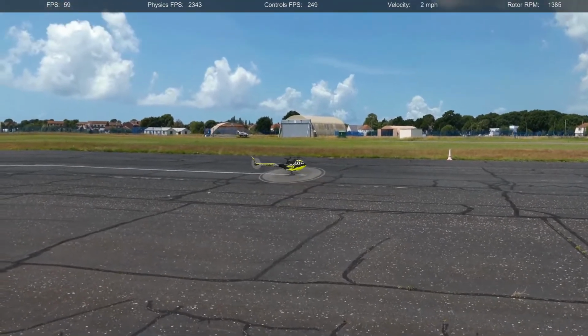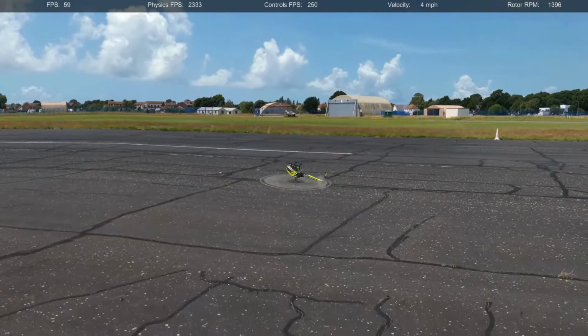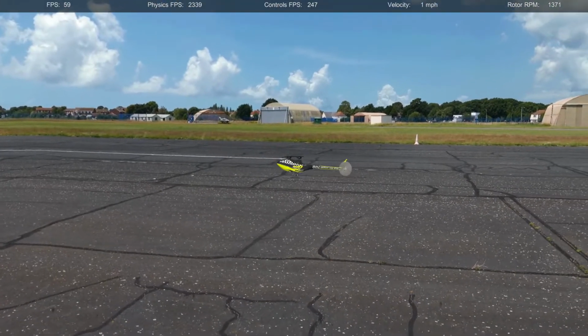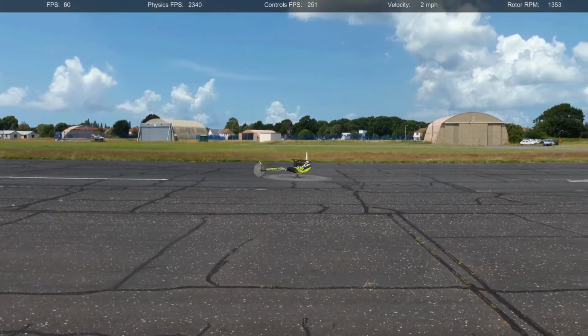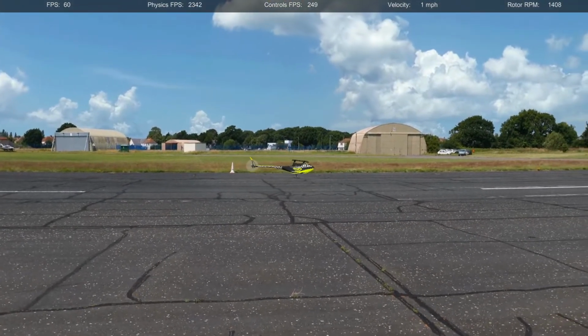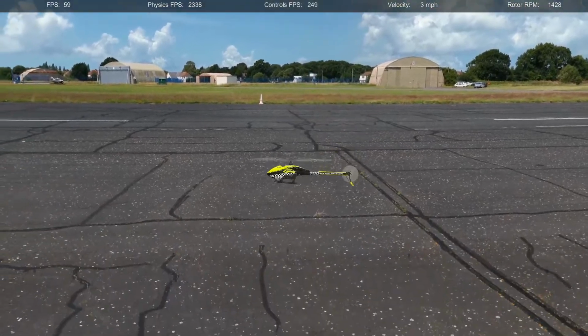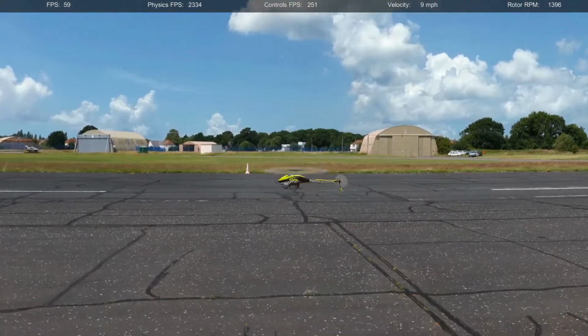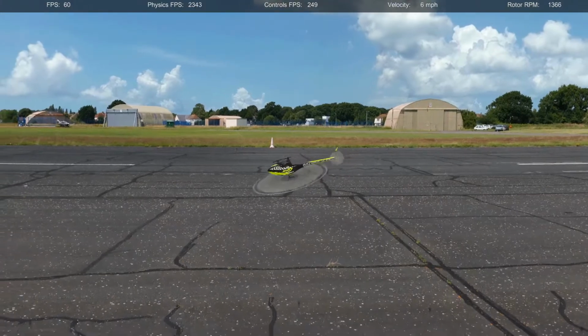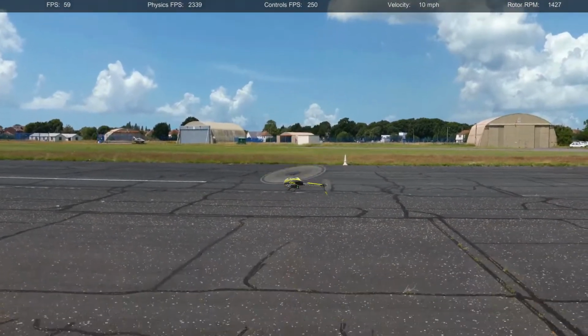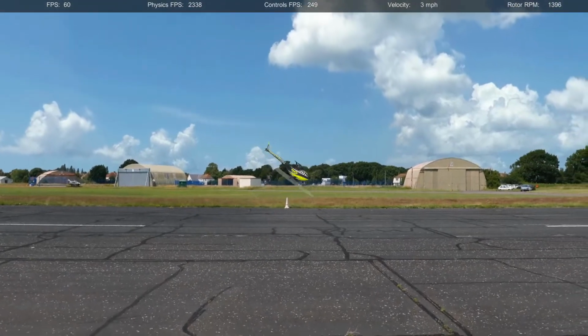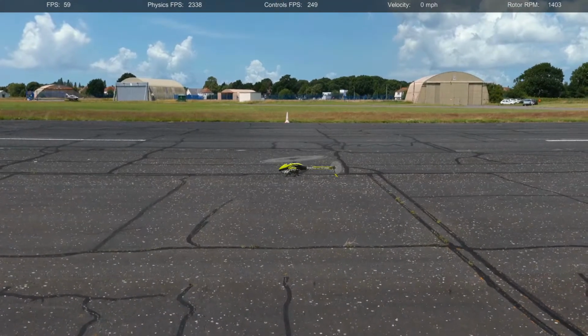And we had to go back and think about this, and talking with Justin was the one that made the observation first. We're sitting there and talking with Derek in the lab, and it turns out that if you unload the tip, all the noise comes from the tip. And so you want to actually reduce the angle of attack at the tip of the prop in order to reduce the torque. You don't want the lift to carry all the way out to the tip.